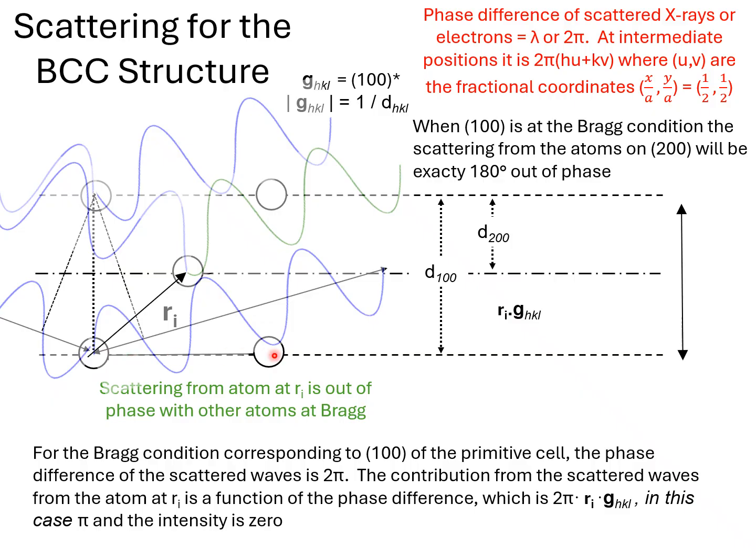So if our Bragg diffraction is set up to be consistent with coherency for reflection from the plane defined by the one-zero-one Miller indices, then the planes which would otherwise be at the two-zero-two plane spacing, at that same angle, are scattering with a phase such that these waves cancel with these waves. So we're exactly 180 degrees out of phase.